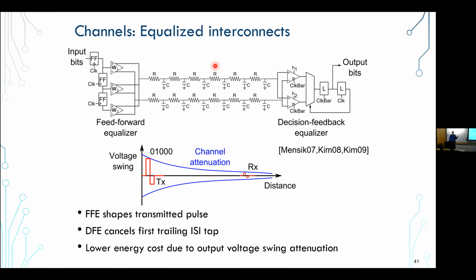This has to be like 1E-18, 1E-20 type of reliability. So it's still a very, very high signal to noise ratio, even though you're lowering the swing. So you always have to keep that in mind. That's why people look at estimating what's the supply noise they're getting on these things, putting regulators and all sorts of things to minimize that so they can shrink the swing and recover the energy.